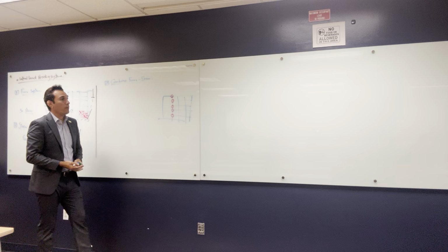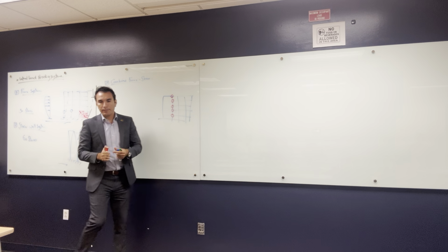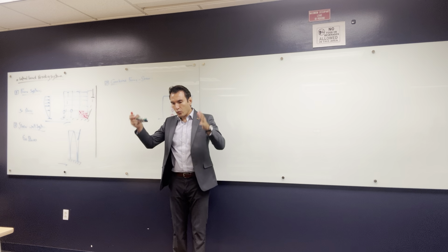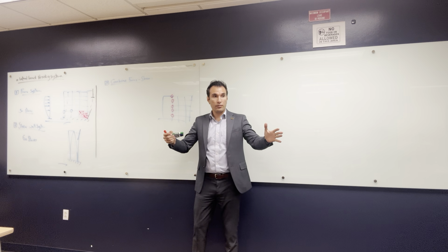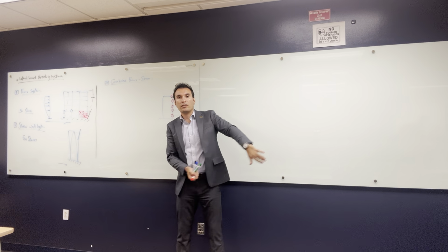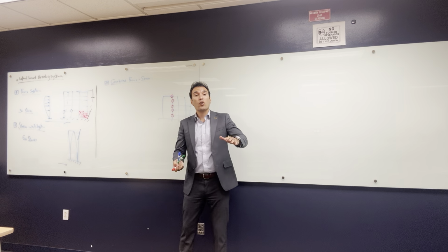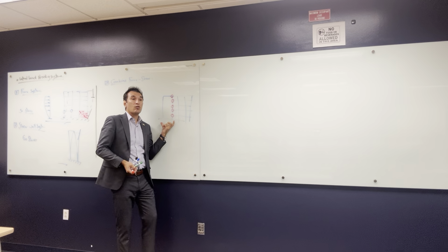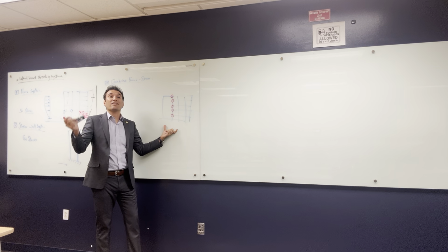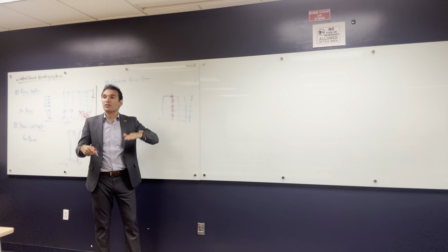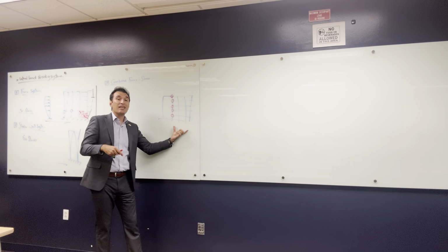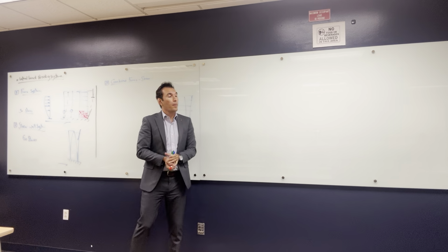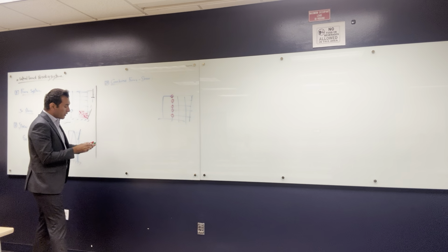So it's all about, let's say that you are designing a building with shear walls and columns, and there's 100-ton lateral force hitting the building. So it's better to distribute the 100 ton between the shear wall and the frame, so that the cross section of the shear wall and the reinforcement of the shear wall can be less, so that you can decrease the cost. And at the same time, you make the columns and the frames take part of the load. All right, so that's for the combined system.